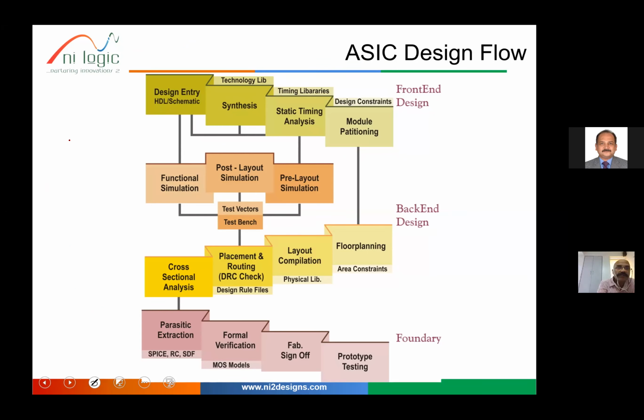For simplicity, I take an AND gate. You want to describe this AND gate, so how do you do the design entry? Either you make a schematic that there is one input A, one input B, and the output is called Y, and these are my IOs. This is how my schematic will look, so this is my schematic design entry.